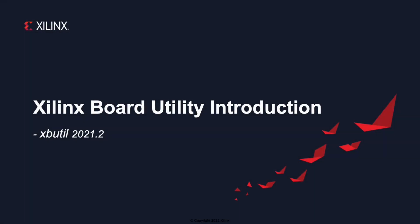Welcome to this quick take video on Xilinx board utility introduction. In this short video, we will walk you through the basic steps of using xbutil to check and validate your Alveo card. You will also learn how xbutil can help you with installation, bring up, and deployment of Alveo cards.